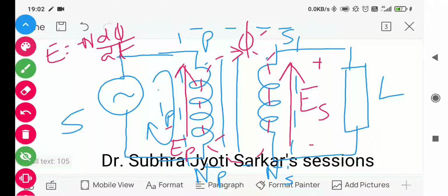So we have EP and ES. How would they be related? EP would be NP d phi by dt, ES would be NS d phi by dt. So the relationship EP by ES is nothing but NP by NS. This is going to hold true.